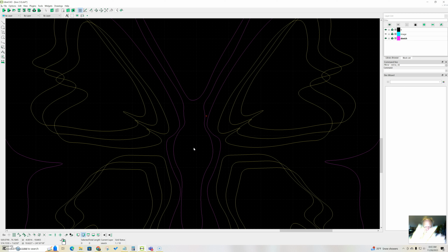So keep in mind, I have my wings linked with these sort of jewelry links. Okay. So we need to do that. I'll say that the links that I have in the lab, in the classroom, 1 millimeter was a little tight and it just didn't quite work as well as I'd like. So the holes have to be a little bit bigger than that. So I'm going to say probably about 1.3 or 1.4 millimeters. Or even, well, let's go with 1.2 maybe. 1.2, so a radius of 0.6.